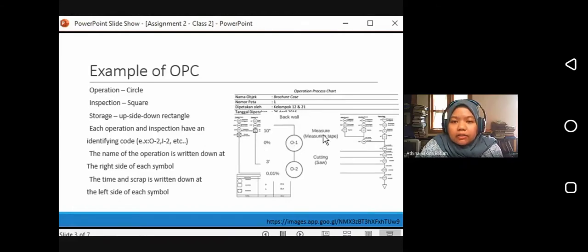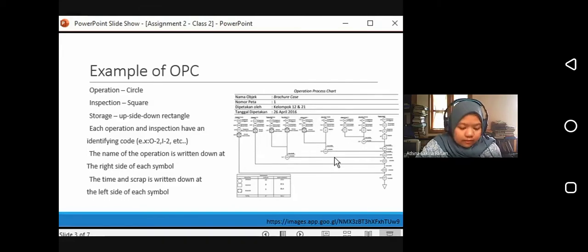And probably can you see the, okay, wait, here. Yeah, this one. The small horizontal line that goes into the operation is symbolizing that you use a supporting material to connect or to assemble the two parts. So for example, here, let's say this is item 3 and this is item 4. To connect item 3 and 4, you need something. Let's say you use glue, then you write down the glue here, and then it becomes another part.